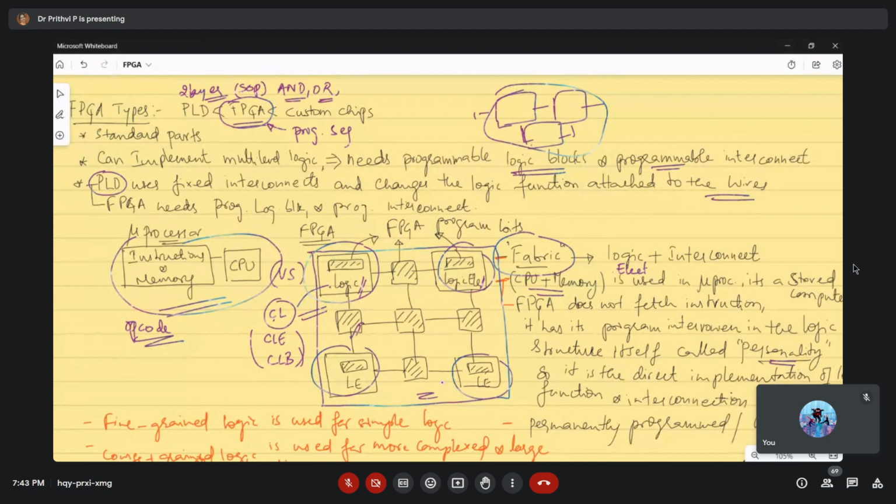So these FPGAs are programmable, we say. Why? Because the structures are standard parts. We try to program according to our need or our logic by properly interconnecting those standard elements. What can be the standard elements? The logic gates, the operators, ALU operations, all those will be incorporated in the standard parts.